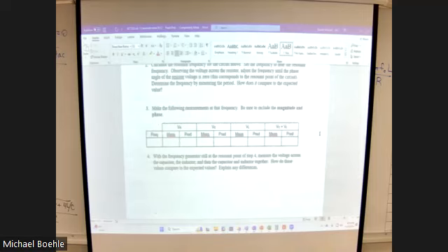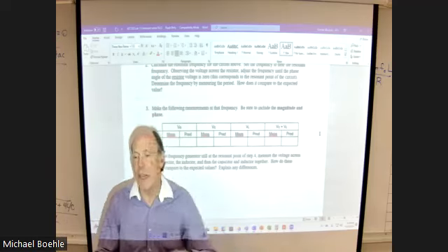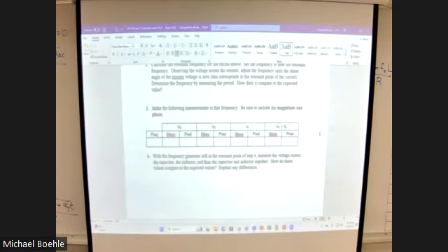And you're going to measure the voltage across the resistor, the capacitor, and the inductor, which means, right, as you learned from lab 8, where you did this same circuit, might have been a different capacitor value, you're going to have to move the components around to measure. That's probably the easiest way to do it, right? If you just use wires, plug it in, and then just move the component you want to measure. And at the end, you're actually going to measure the voltage across both the capacitor and the inductor. So they're in series, so you'll just basically measure across the two of them.